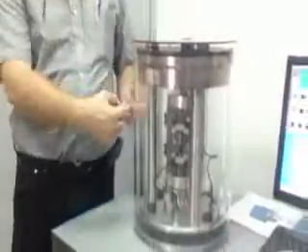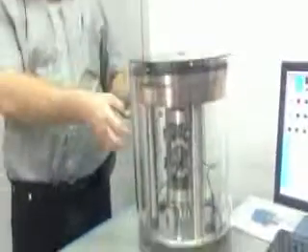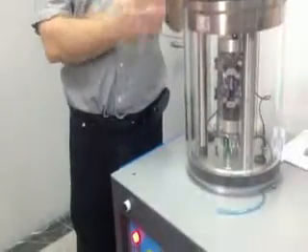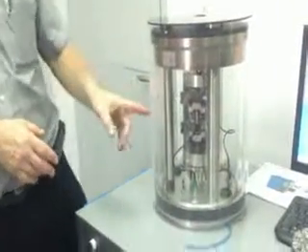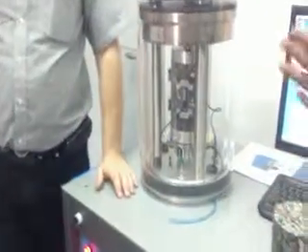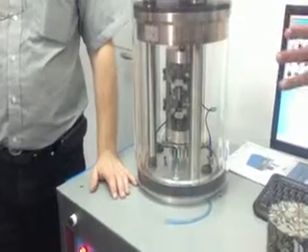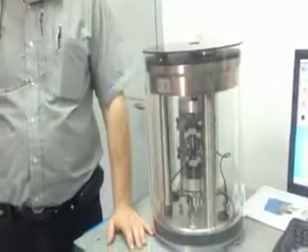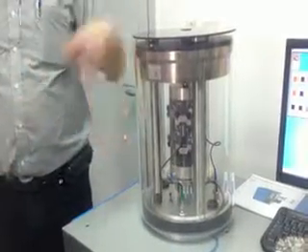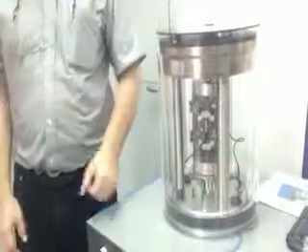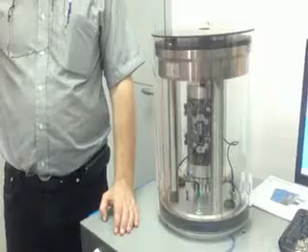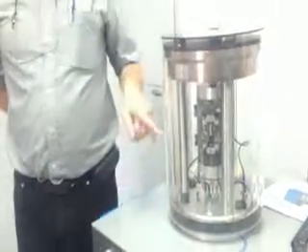If you were doing one sample, you could use this to condition it. But if you're doing many tests, then you need to get all of the samples up to temperature quite quickly. If you're just using one sample, we will start from the cooler one, for example 4, then adjust to 25 and wait till it's conditioned. After that we can be done. No need to put it in the oven; we will wait inside the machine. You can keep it in here, but if you're doing many samples, it can take 1 to 2 days to condition. It depends on the temperature, but you can only condition one sample.